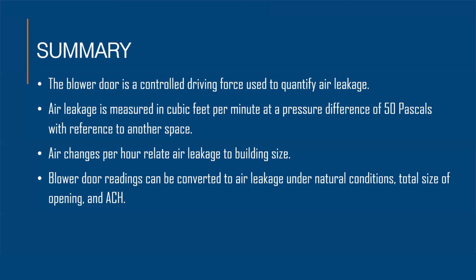Blower door readings can be used to communicate a building's leakage rate a couple different ways. It can be converted to CFM natural leakage. It can indicate the total size of the hole in the air barrier. It can even be massaged into an air changes per hour rate under natural conditions as well.